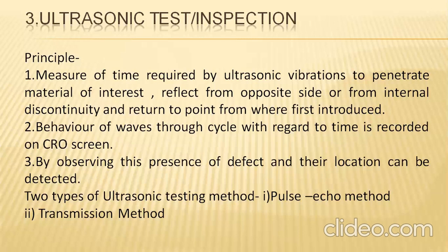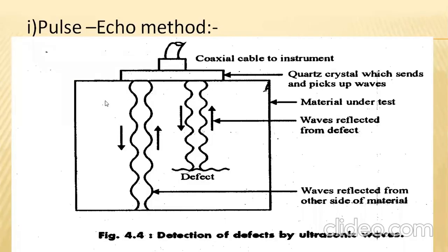The echo effects generated externally are implemented to penetrate through the material, passing through it, and we identify the behavior of the waves, whether they are penetrating through the material or not. This is a clear-cut example of the thickness. In the liquid penetrant test, we have only surface-level defects and only up to a particular thickness, that is 3 mm or 2 mm, like that.